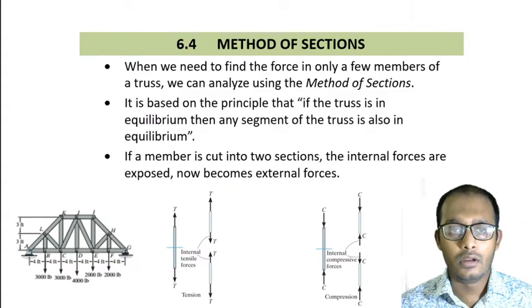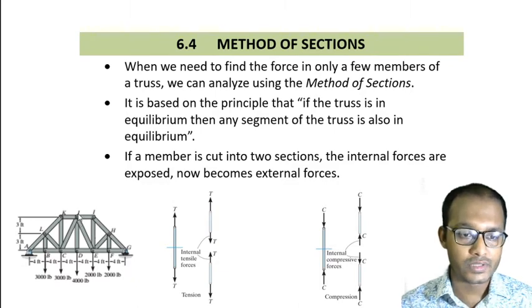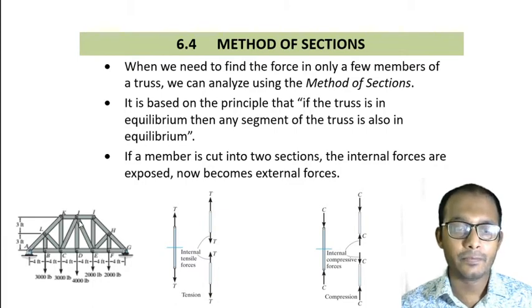So where can we apply this method of sections? Actually, when we need to find the forces in some specific portions. You can see here there is a truss, and if the question asks to find the forces at this member, then it will be a very lengthy process to apply the method of joints to identify the forces at that member.